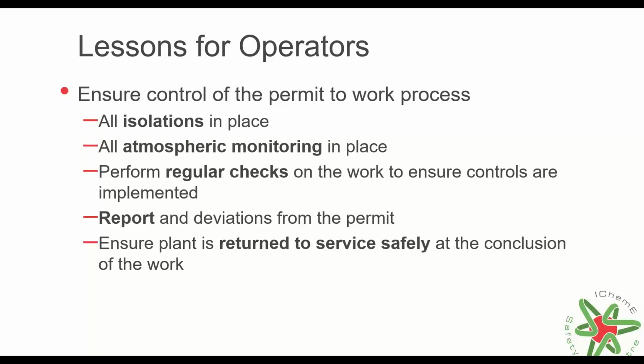It is predominantly the most significant control measure you have when it comes to flammable atmospheres, because it's the one control measure that allows you to introduce an ignition source into an atmosphere that could have a flammable substance present in it. So once we've got the flammable substance, if we're in air, all we need is the ignition source to start up that fire or explosion activity.